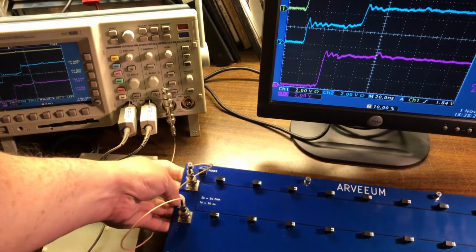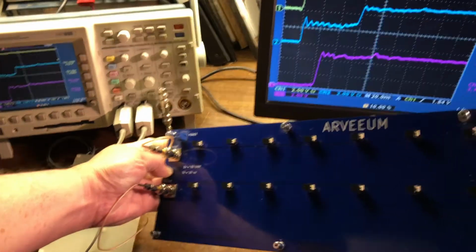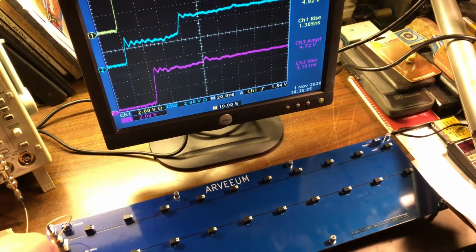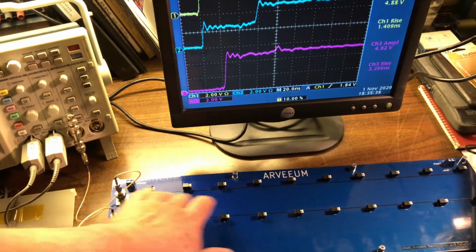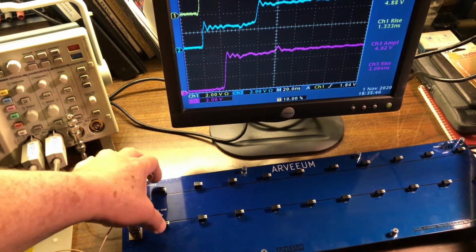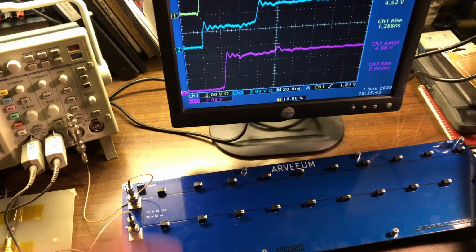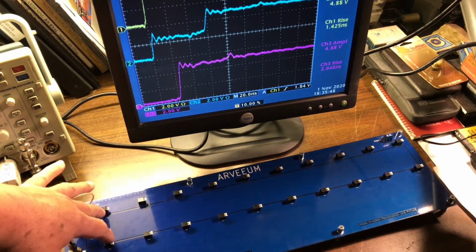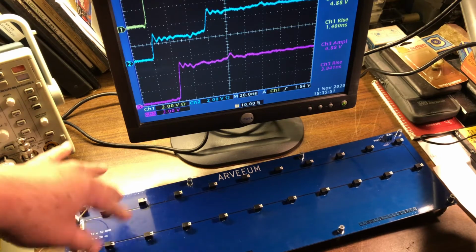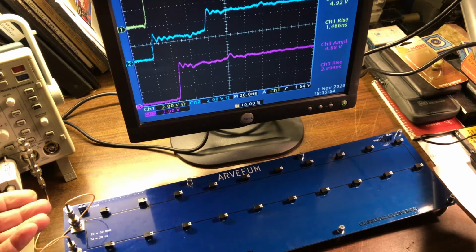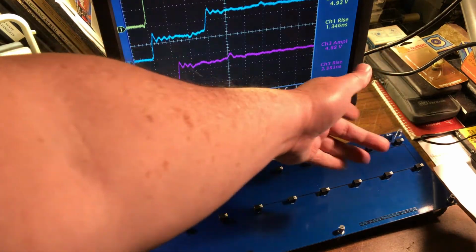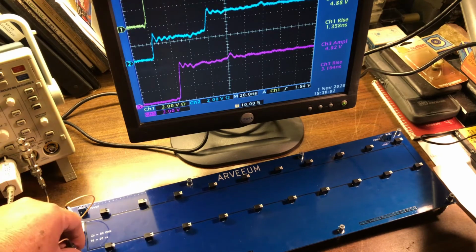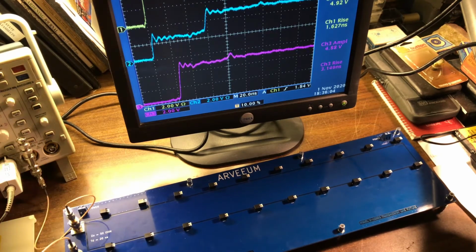The plane is maybe a power plane, like I'm showing you here, this plane right here. So you only need 2 capacitors. The rest, if you have more bypass caps, that's great, but strictly speaking, you only need these 2. And the reason is because the current just hugs the microstrip. It won't go away from the microstrip, it just follows the path of the microstrip from the input connector to the output connector.